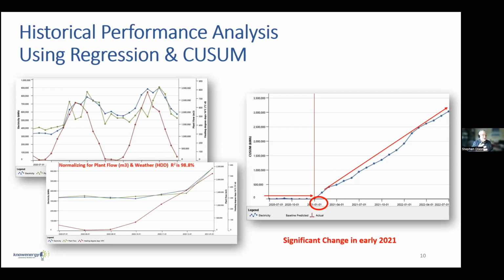Many times, those changes are unknown to the facility, and we've actually discovered opportunities. In one industrial facility, very similar to this one, we discovered that they'd moved to a third shift, and they were using only about 3 or 4 hours of that third shift to make up production. They left equipment idling, and it really wasn't idling in terms of energy. That upturn allowed us to quantify about $250,000 in savings opportunities for simply turning things off. So you can quickly get to this stuff and rapidly audit a facility.